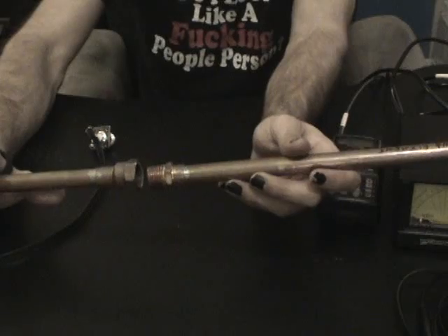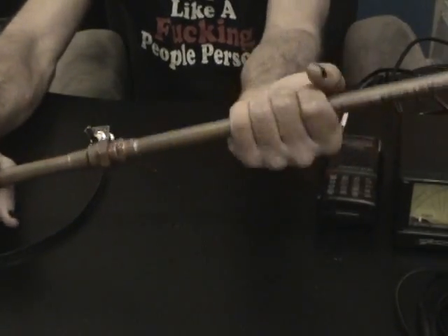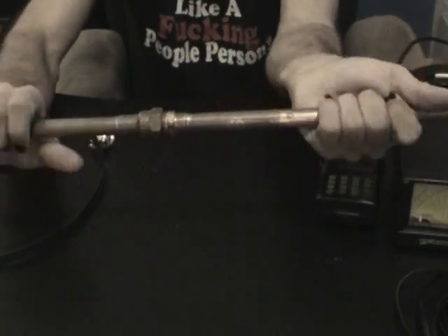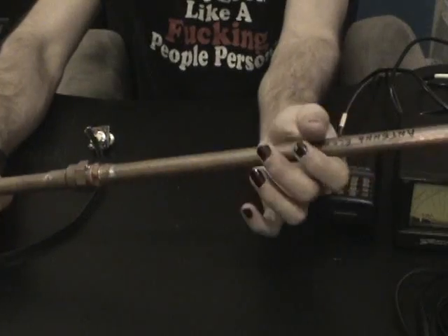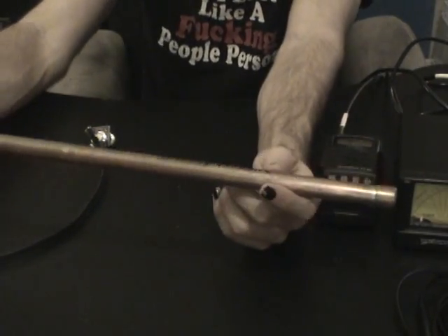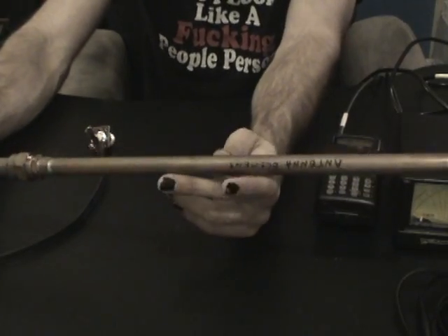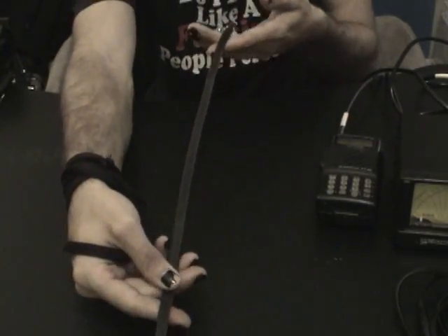Your best bet is to actually sweat solder your connectors on where you like them, and then thread them in, not as tight as you can, just by hand tightening it, and then cut it down to the exact size you need. But we're working with lower frequencies, so it's much more forgiving when it comes to being off measurement. Now, here's the ladder line, or what they call twin lead.